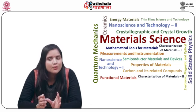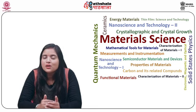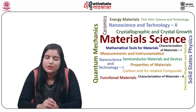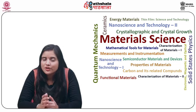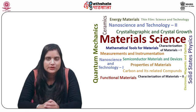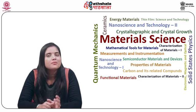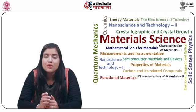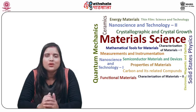During alloy formation using ball mill, two processes simultaneously occur. One is the fracturing and the other is the cold welding of powders. Thus, it becomes imperative to create a balance between these processes for successful alloying.